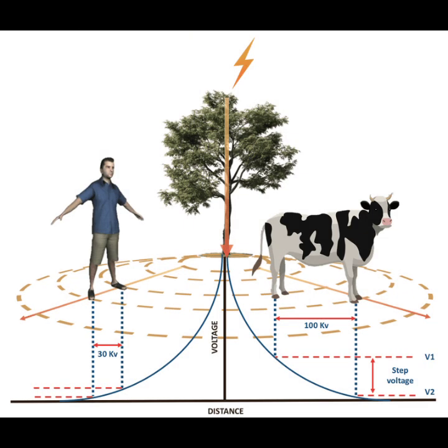Nearby strike. When lightning strikes closely, it can cause ground currents, or electromagnetic pulses that can affect nearby objects. These currents, or pulses, can travel through conductive paths, such as power lines, communication cables, or metal pipes, and cause damage to electrical systems or equipment.